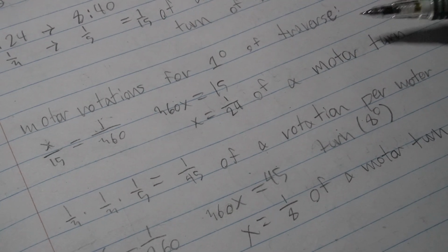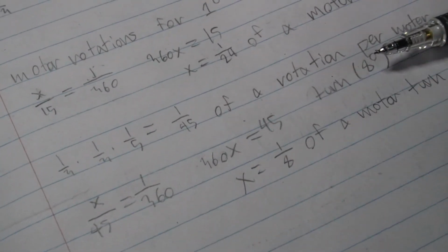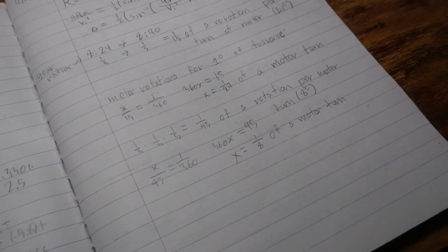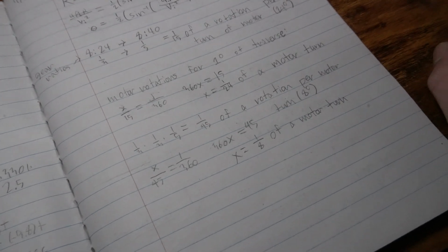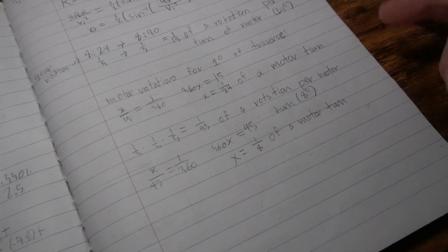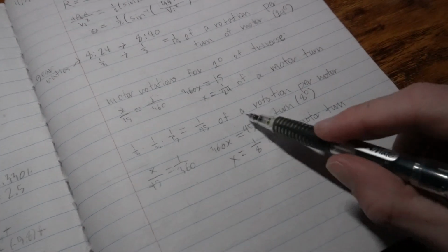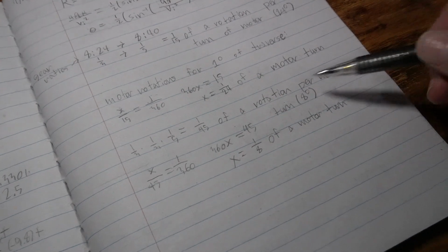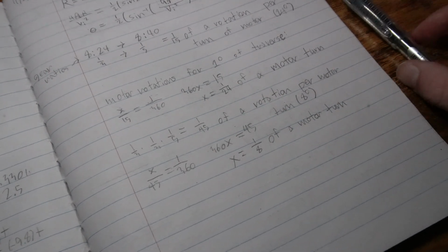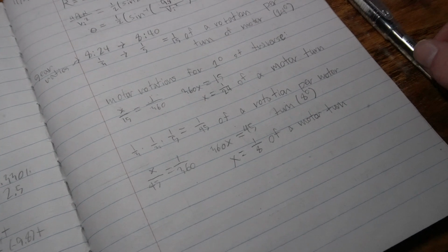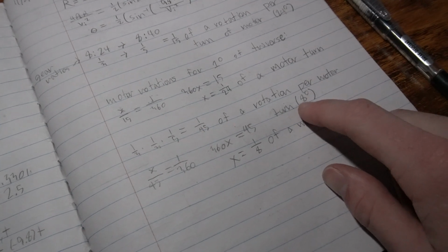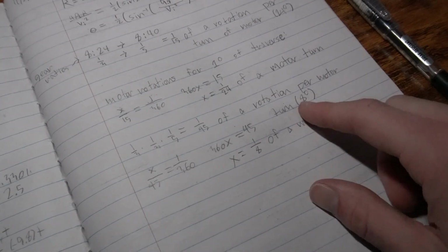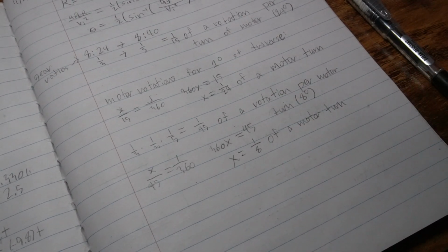So this part is just using the gear ratios that I used to find an accurate amount. So the gear ratio is low enough that each rotation of the motor turns the dart shooter 8 degrees, which is accurate enough so that the motor is accurate within a quarter turn-ish, sort of. So that means it would be accurate to a quarter of 8, which is 2 degrees, which is good enough for my application.